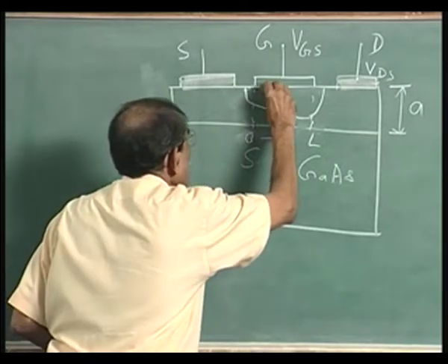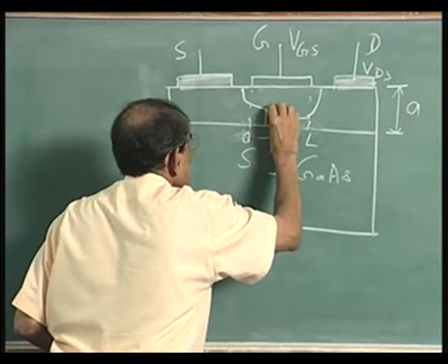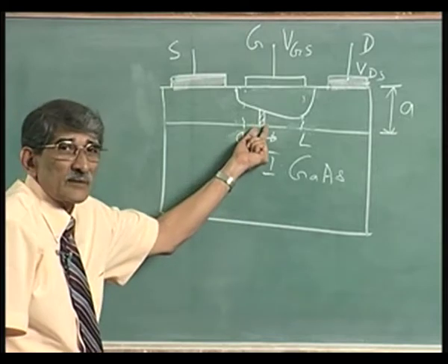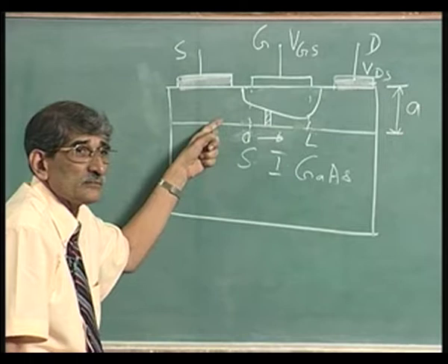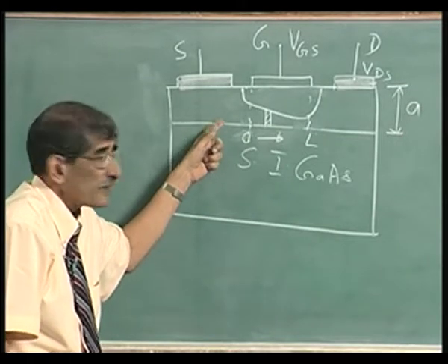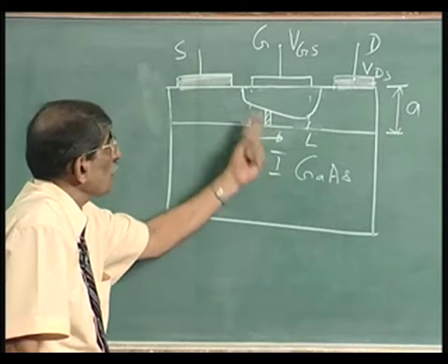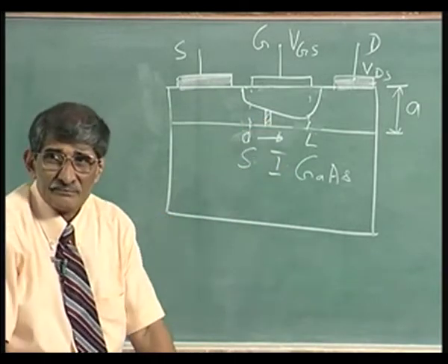So, what we do is take a strip here of width d of x, find out what is the drop across that due to current I d, because current is constant right through, there is no current accumulation. So, find out the drop I d into rho d of x divided by area of cross section, that is all what you are doing.